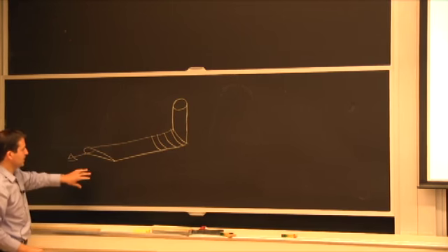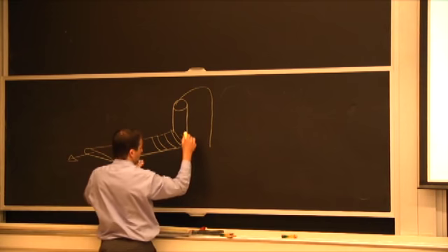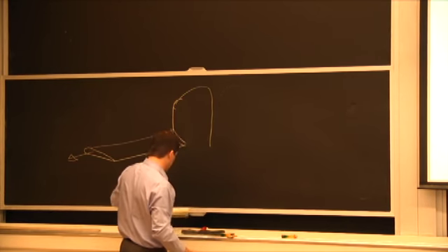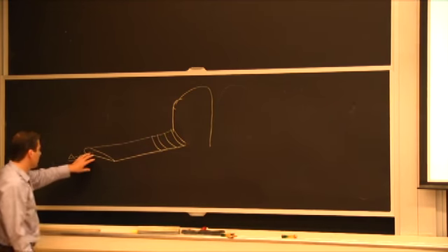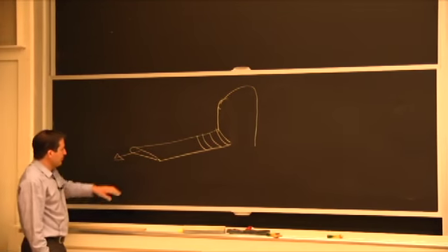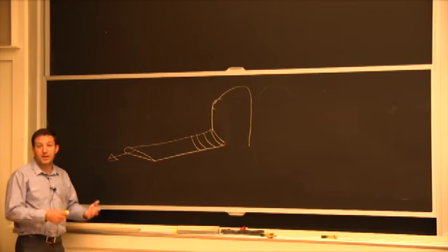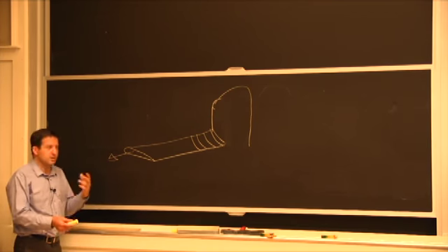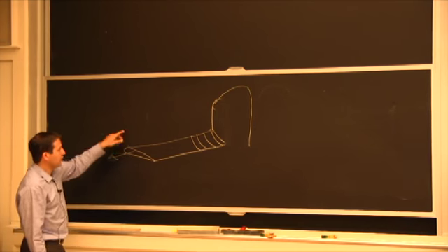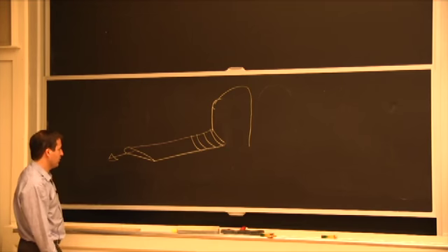We're not doing all the way to the end. Let's say we're doing relatively close to the rotor. So we're going to make the rotor a little bigger here. So we're close to it. It's a tapered section. Say we've identified one of the regions of highest load. The centrifugal force, well, it's the rotation speed. So we can get a good estimate from that, based on everything we know about the design, how much aerodynamic, the force of the engine. So say we come up with a maximum value for that.